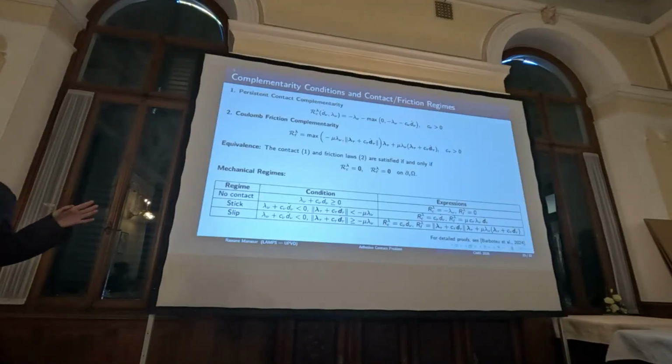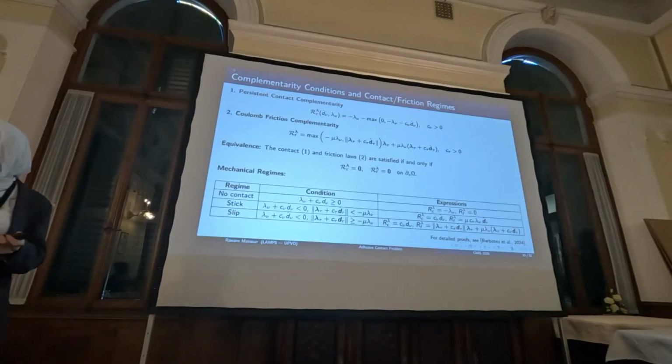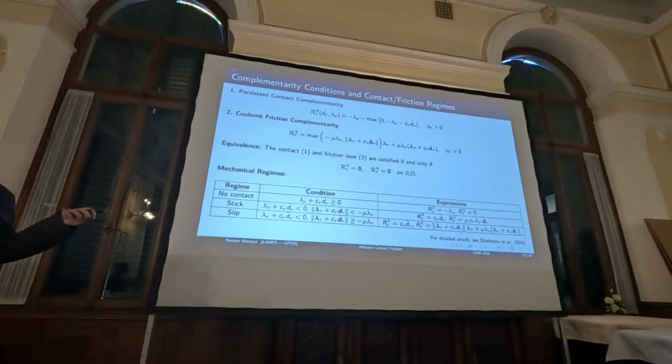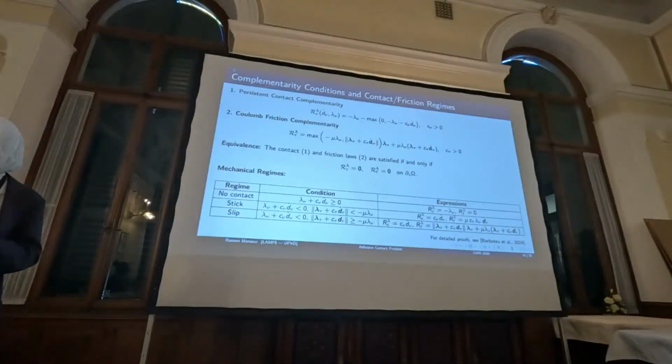For our model, we have the unilateral contact, represented by R lambda C, while friction is represented by R lambda F. We have not one complementarity function for the two models. Yeah, for instance, for the normal contact condition, you could have chosen Fischer-Burmeister or some other forms. Yes, it's just for simplicity, we use the simple form for contact and adhesion, and for viscosity, we use a simple model.